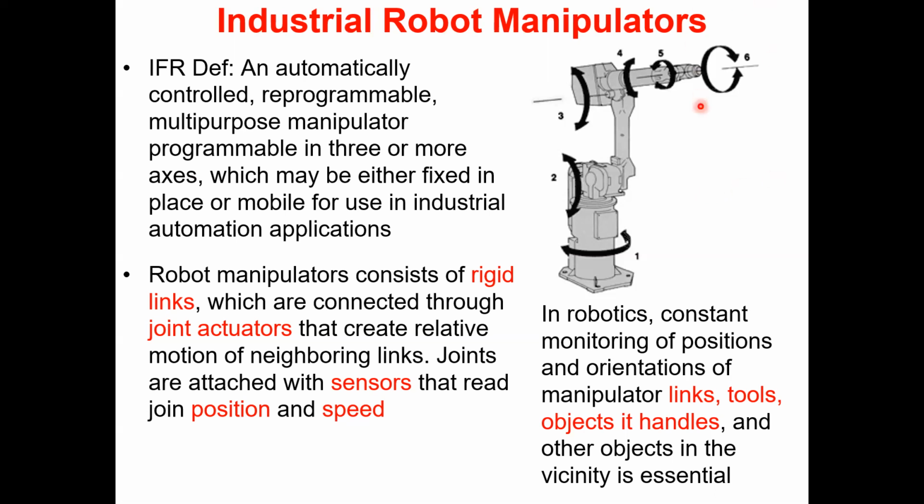But with 6 degrees of freedom, 6 variables, you can do that. If you have only a few variables, maybe 3 of them, you can't control the end point and position it with the desired orientation. With only 3 joints, you can't do that. In order to orient it properly and control the position, you need about 6 degrees of freedom.